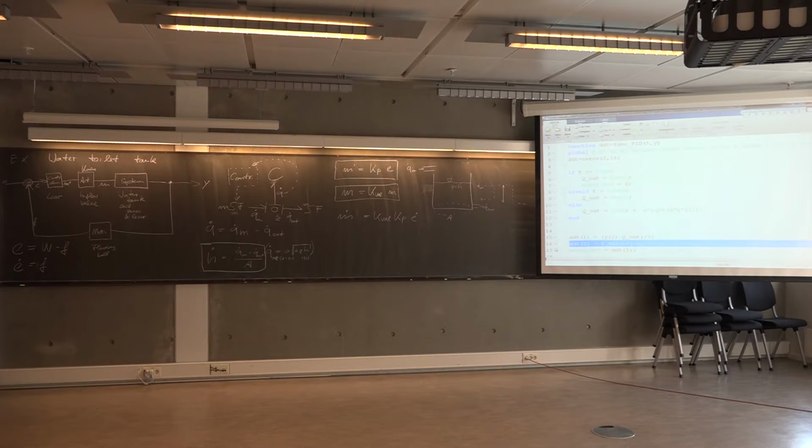And by setting the numerical values of Kp, Ki, and Kd to 0, you can basically create any of the previously mentioned controllers, right? If you set Kd to 0, meaning the derivative term to 0, the result is just a PI, a proportional integral controller. So this PID controller is the most versatile, the most generic form, and you can basically generate all the others from this one.